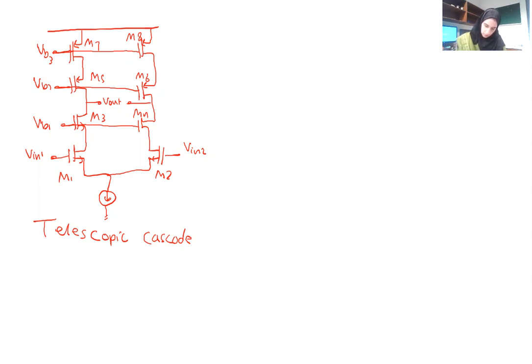Okay, so now we want to find the gain of this telescopic cascode. Since it's identical on both sides, we can draw a line of symmetry. And any point on this line of symmetry crossing is going to be a virtual ground. Now, somebody might ask, what about those lines which I drew here? In any case, those are biasing points, a DC point that will turn out to be AC ground in the small signal.